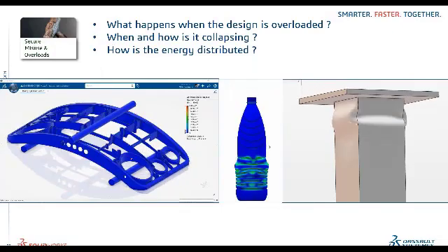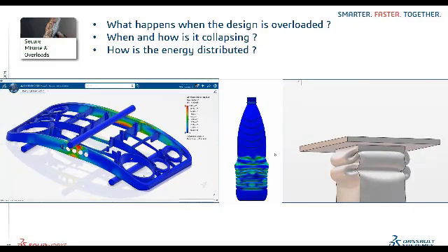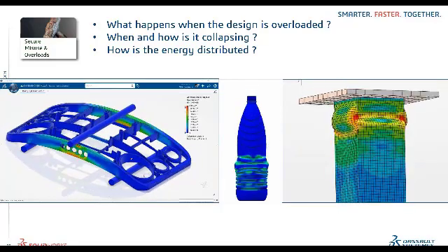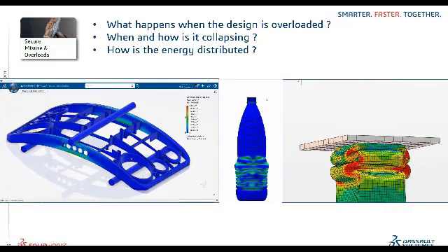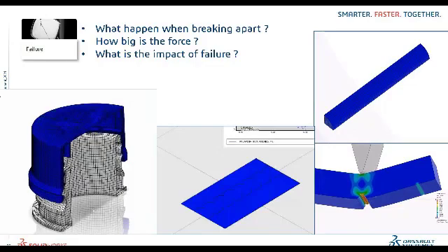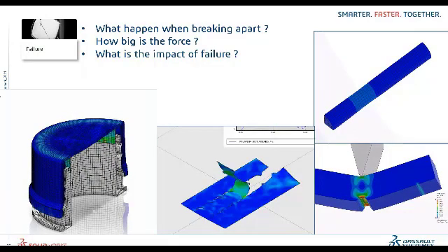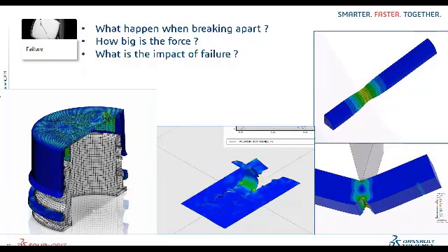And then we have misuse and overload. You can do the buckling analysis, crush analysis, and we have different sets of rigid and flexible body combinations. All these phenomena and analyses can be performed. And then different types of failure. For example, Johnson-Cook failure methodologies can be implemented, as well as ductile and brittle material failure phenomena.